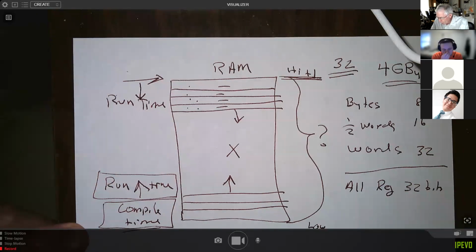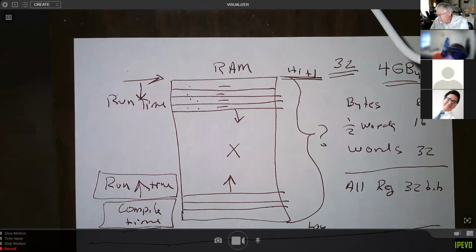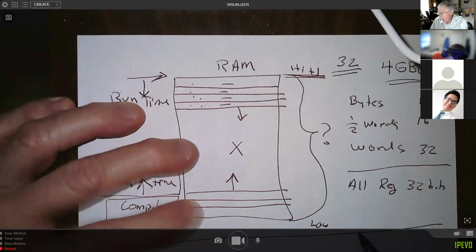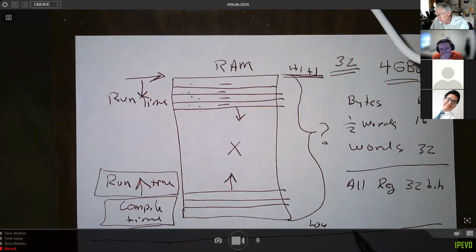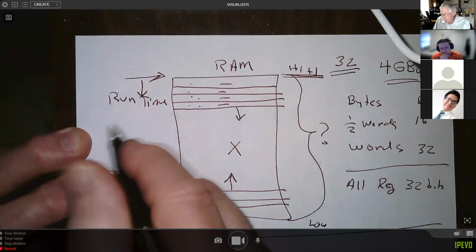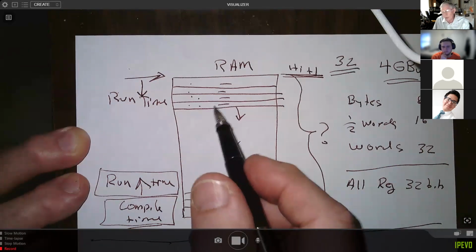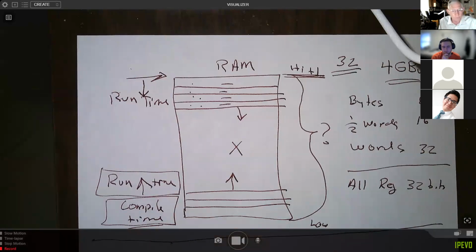So anyway, this whole stack thing, generally you're going to stay out of trouble because you've got a lot more RAM than you probably will ever need. But if you put in a lot of defined variables that are, say, global and are going to be static, you could theoretically get in trouble with the RAM. The other thing that makes this all unpredictable is interrupts. Every time you have an interrupt, it also uses the stack, and it pushes on not just the return address, but it pushes on all the context saving for all the various registers.